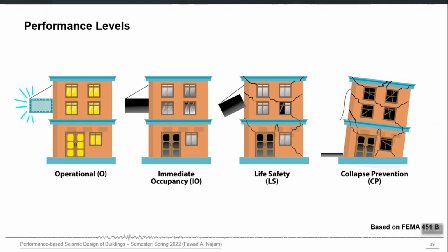So in the new building code of Pakistan, you will see hazard maps at different probabilities. DBE level, MCE level, SLE level, and some intermediate level also, because for bridges generally the design hazard level is somewhere between DBE and MCE for buildings. It is a 1000 years return period, which is somewhere between DBE and MCE for buildings.